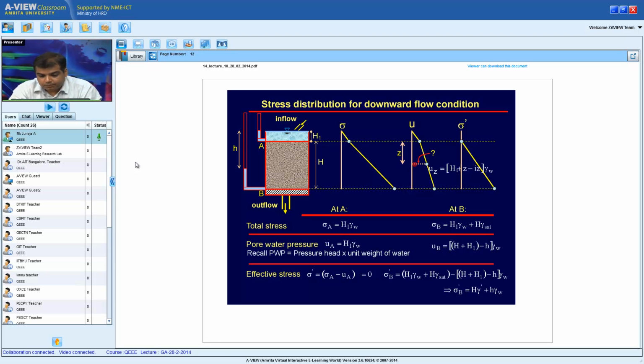We are going to do a problem next time on this matter, just to understand this carefully. Meanwhile, I would like you to spend more time looking at it carefully when there is downward flow. For the students, what I normally say: downward flow, the pore water pressure always decreases. Remember, downward flow, pore water pressure will decrease. Upward flow, we're going to look at in the next case.